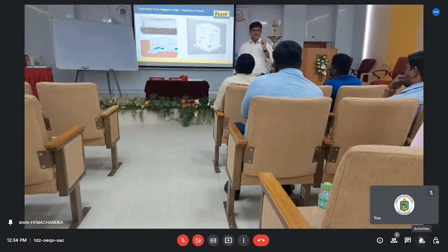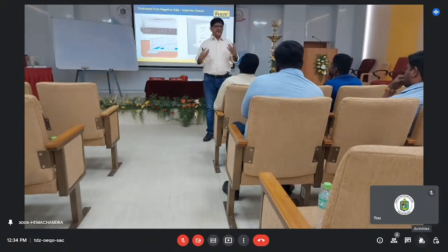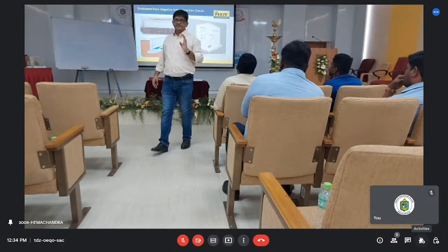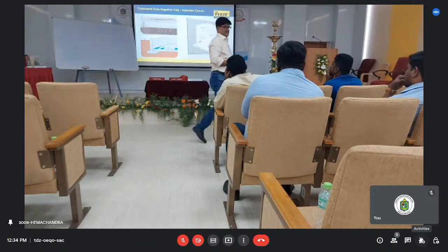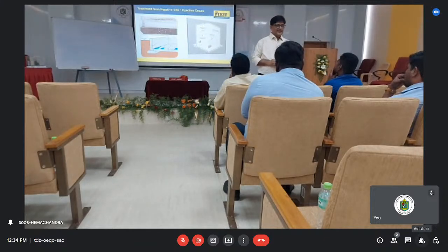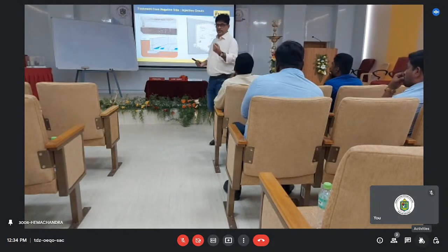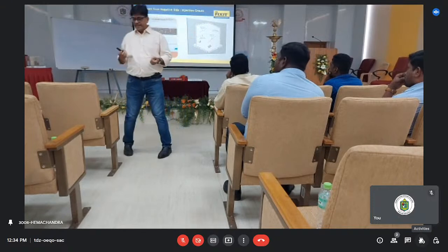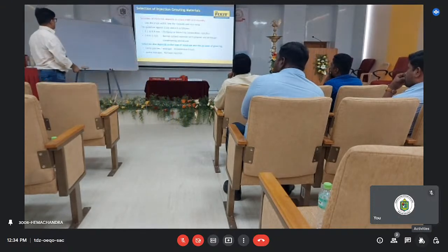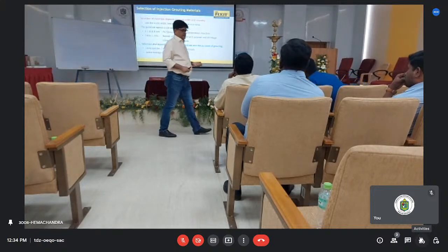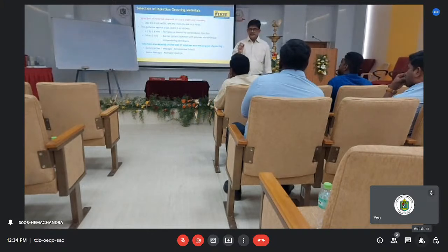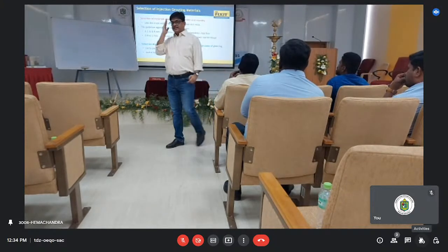Now, what to select? Important is that everybody will tell you what they make. If I am a manufacturer of a PU grout, I will tell you, sir, do the PU grout. If I do not have a PU grout and I have an epoxy grout, I will tell you, sir, do the epoxy grout, and that's the best way of getting the solution. Am I right? But as an engineer, this is not the best way to get the solution. So I should know the logic of when we have to use what. So for injection grout, the first thing is the selection of the right injection material. When you are dealing with cracks, you have to understand if the crack width is minimal and it has a depth underneath.